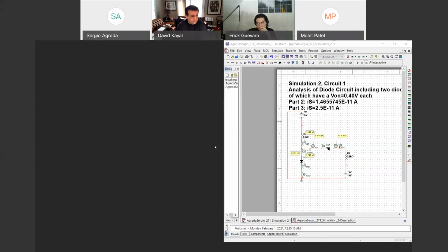Voltage on, which he'll get to explaining in class, is basically the voltage drop across a diode in a circuit when current is running through from its anode to its cathode. It's basically like a resistor that has a set voltage drop, but it needs a certain voltage to break through it to then have a set voltage.